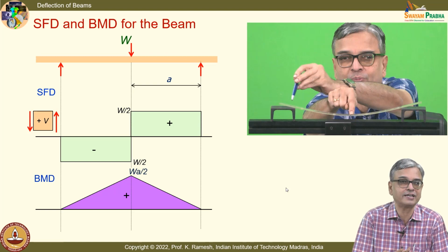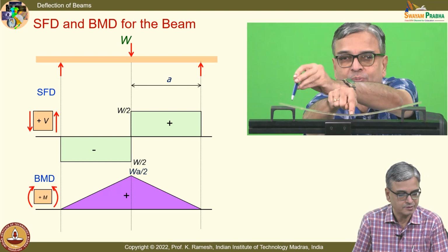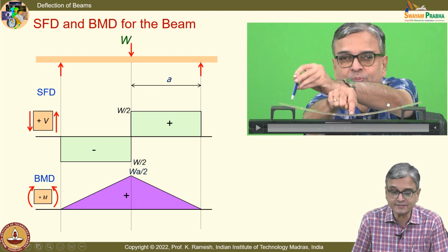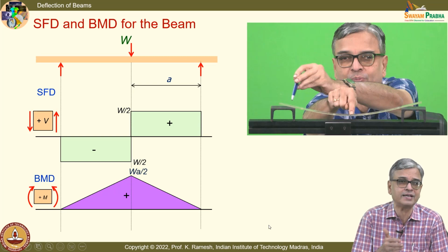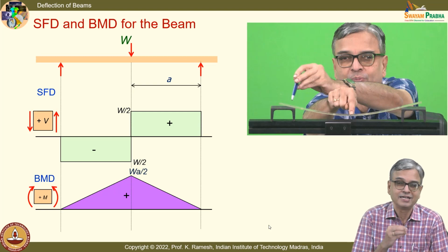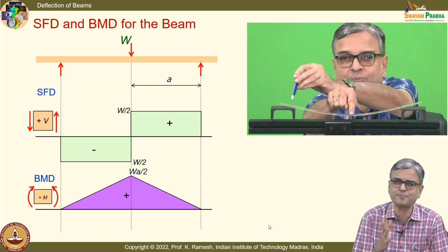We have the moment curvature relation. We should write what the bending moment at a section is, apply the boundary condition and get the two integration constants. And I have also shown the sign convention that we have been using in this course. So, everything is complete about this problem. So, you have to visualize. The idea is, in certain simple problems, I will give you the picture here. That should give you a training. When loads are given, you should be able to conjecture what could be the deformed shape. Looking at the support, looking at how the beam is loaded, you should be able to sketch it at least approximately.